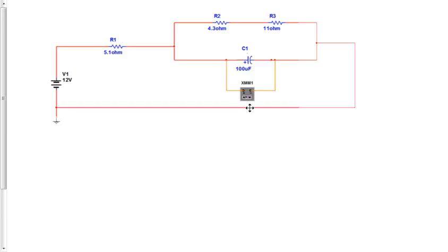Now, in a steady state condition, this capacitor is going to be totally charged, and the current on this branch is going to equal 0, because when the capacitor is totally full, no charges will pass through. So really, electricity is going in this line here, which is a simple series circuit then.